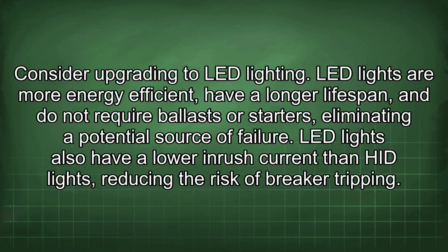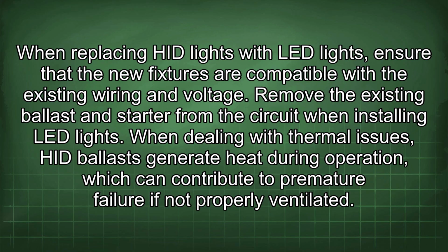LED lights are more energy efficient, have a longer lifespan, and do not require ballast or starters, eliminating a potential source of failure. LED lights also have a lower inrush current than HID lights, reducing the risk of breaker tripping. When replacing HID lights with LED lights, ensure that the new fixtures are compatible with the existing wiring and voltage. Remove the existing ballast and starter from the circuit when installing LED lights.